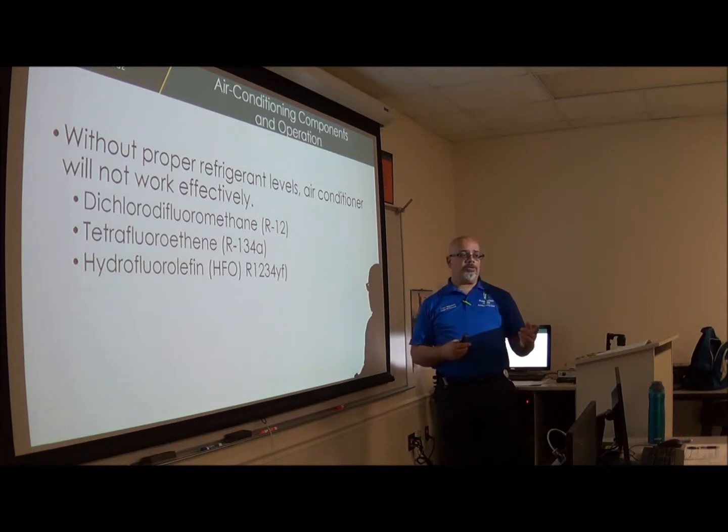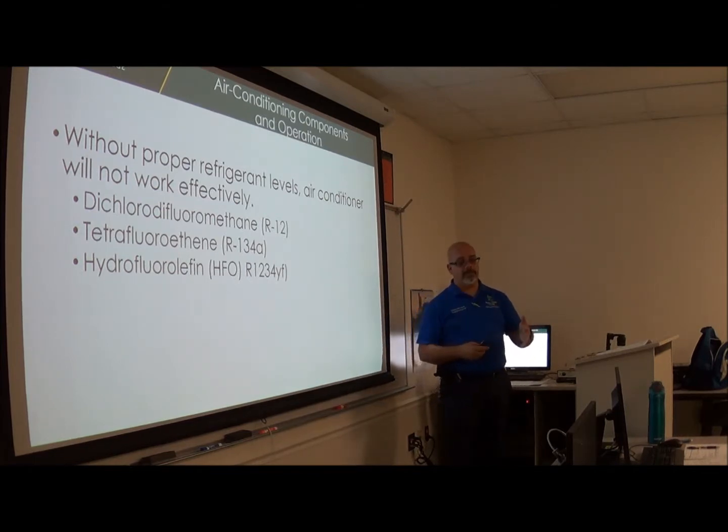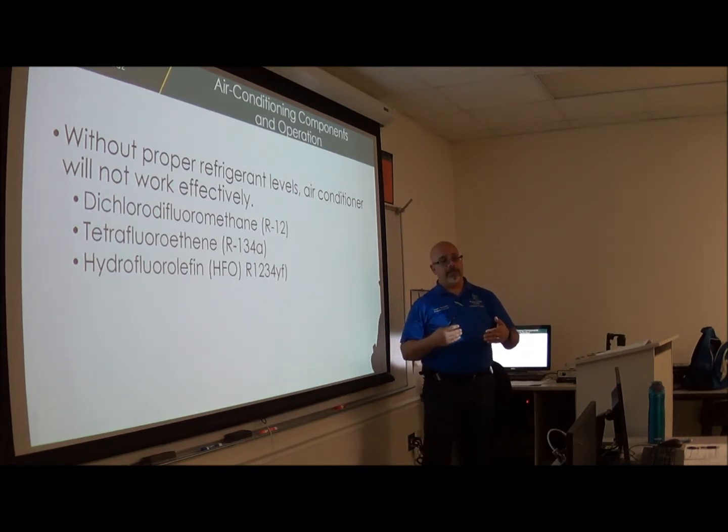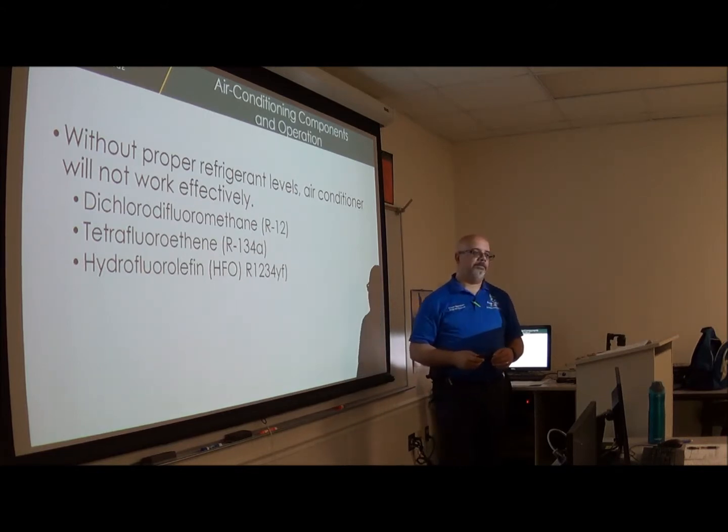Correct. That also happens if the fan in the condenser is not working properly when you're stopped at a signal, if it's lacking power. That does not let it cool down enough, so you do not receive that cool air when you're stopped. And then when you start running, since you have that air coming in naturally, it cools down again. So that's because you have problems with the fan.